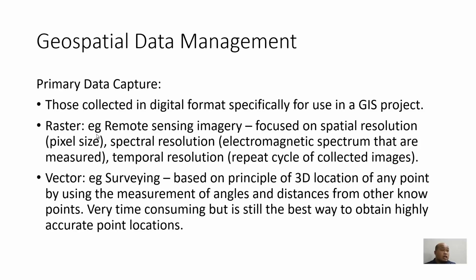The RGB is the true color, while the infrared is the false color. We incorporate the near infrared or any other microwave spectrum or radio spectrum. There are many spectrums available, right? We take that spectrum and put it into the RGB. That is what we call the false color. So with the help of false color, we can actually conduct studies, right?